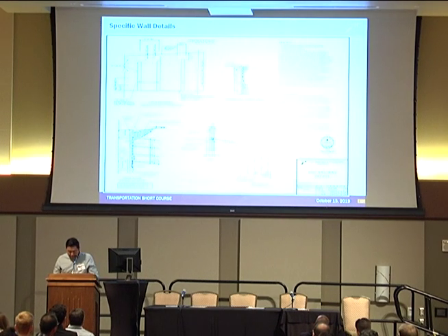As I said, this is not standard. We do not have a soil nail retaining wall standard. It's not like RW-MSE or the RW-MSE-DD. The soil nail retaining wall should be designed for each site condition and soil condition. So the plan notes in the soil nail layout have lots of information.